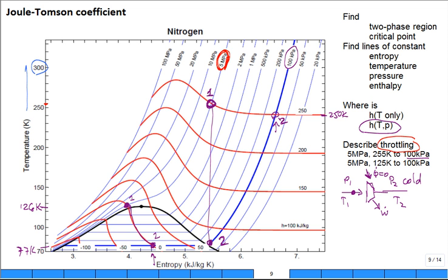Let's say you don't have a really good turbo expander. Let's say its isentropic efficiency is not 100%, which is shown right here, but it's 80%. Where would state 2 be then? It would be over here somewhere. Oh, I'll still take it. The isentropic efficiencies of some of the first turbo expanders, I think, were in the range of like 30% or 25%, which means they probably were kicking over here, which is still a whole lot colder than before, just putting it through a restriction. And then they kept improving and improving because you can get it to so much lower temperature.